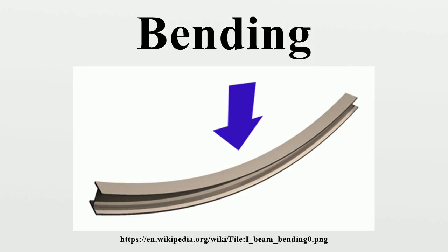Timoshenko-Rayleigh theory. In 1877, Rayleigh proposed an improvement to the dynamic Euler-Bernoulli beam theory by including the effect of rotational inertia of the cross-section of the beam. Timoshenko improved upon that theory in 1922 by adding the effect of shear into the beam equation. Shear deformations of the normal to the mid-surface of the beam are allowed in the Timoshenko-Rayleigh theory.